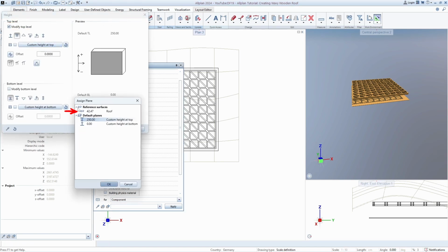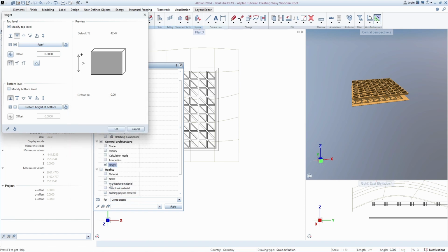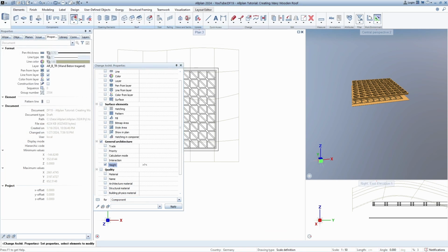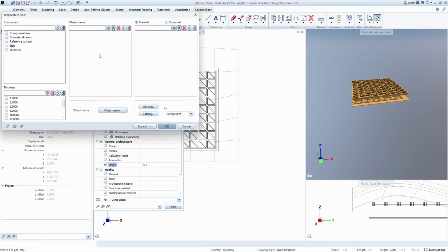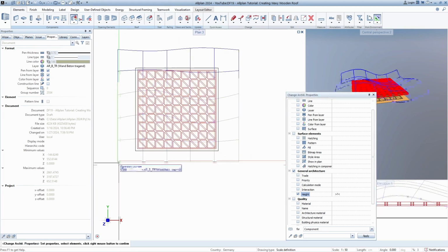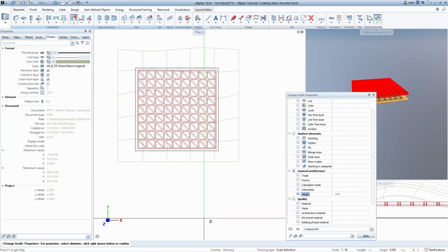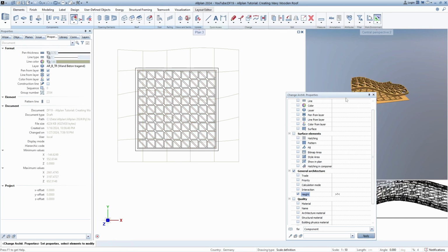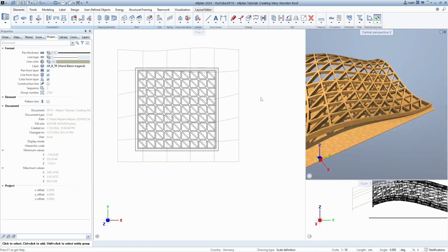After that, select our new plane roof and then start the filter by architectural elements, where we will include our beams. Let's cover everything with the selection window, and Allplan will consider only the beams. Finally click apply, and if your computer freezes, give it some time to process the entire model.